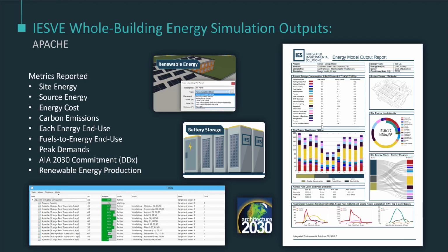So you can see here I've got an EUI of 24. However, over here I've got an EUI showing to be 17. That's because this EUI graph is including the effects of renewable energy sources. So that's why there's a thick inner ring inside of the thick outer ring. So the thick outer ring here is basically the pie chart of energy uses, and the inner ring is energy contributors. So usage was an EUI of 24, but with renewables it drops down to 17. Now that's how to look at energy holistically, or carbon holistically. If you want to look at it on a month-by-month breakdown, you can get this stacked bar chart.